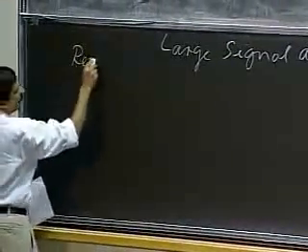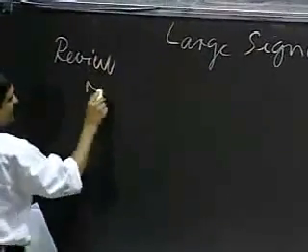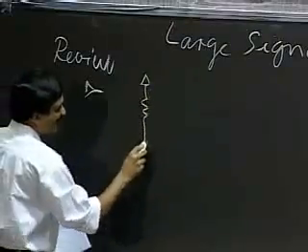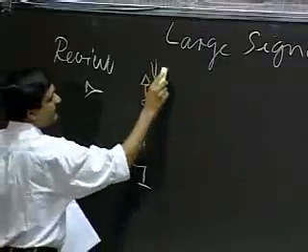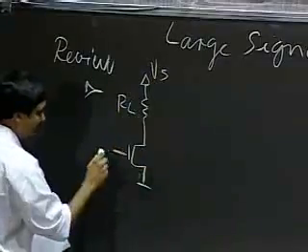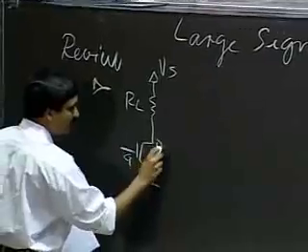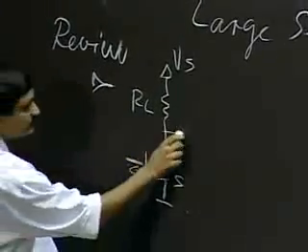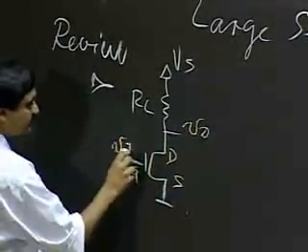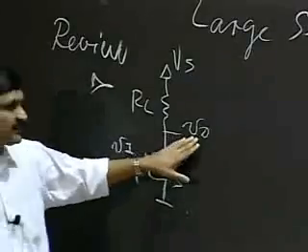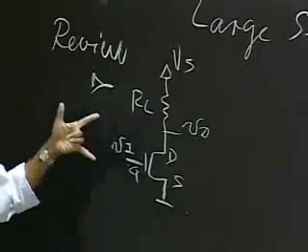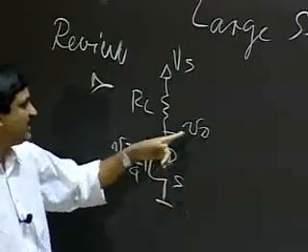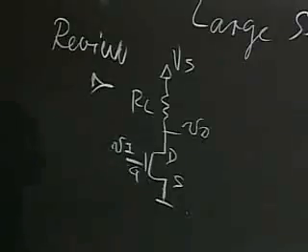So to quickly review where we've been so far, we looked at this little structure here, our MOSFET amplifier. Notice that when I write a voltage at a node, that's a short form for saying that I'm looking at the voltage between the ground node and the node at which the voltage is written down.